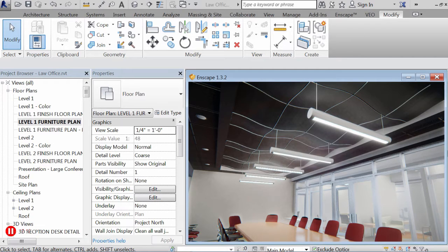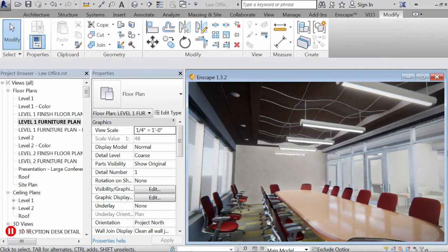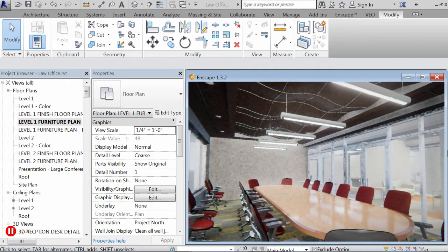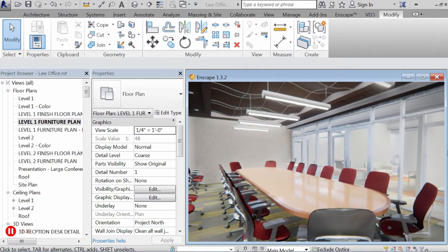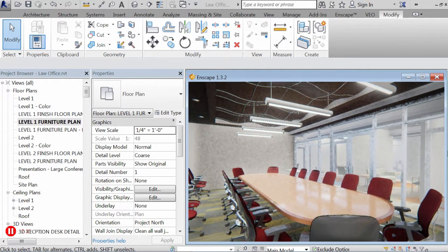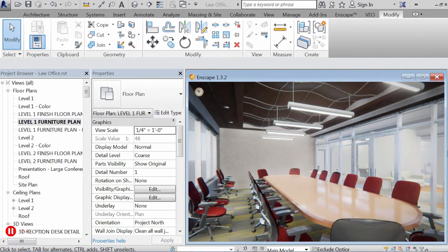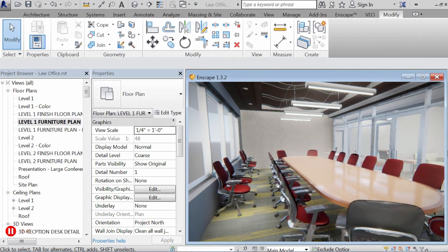But now we're getting to the point where a lot of manufacturers are starting to make content, plumbing fixtures and furniture and these types of ceiling tiles and light fixtures as well, and the light fixtures having the ability to attach photometry to them and really do real world point-by-point illuminance calculations in Revit using a professional add-in like Illum tools. There's a lot of really cool options.